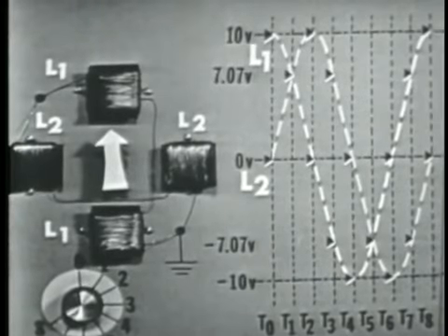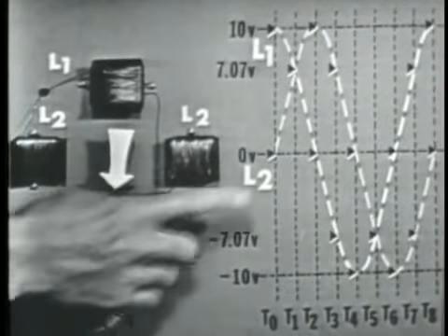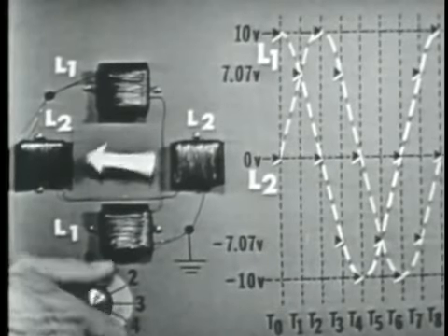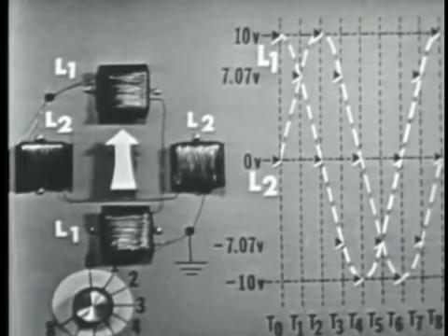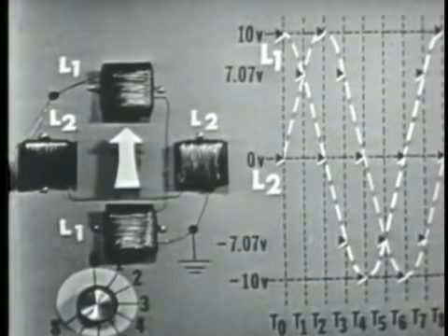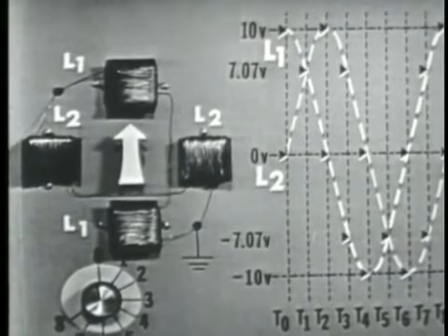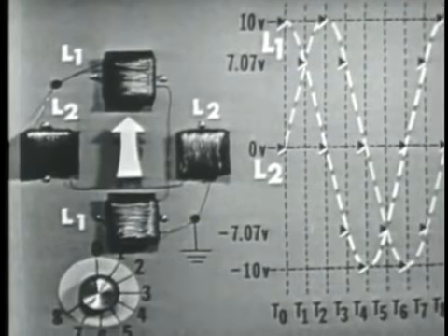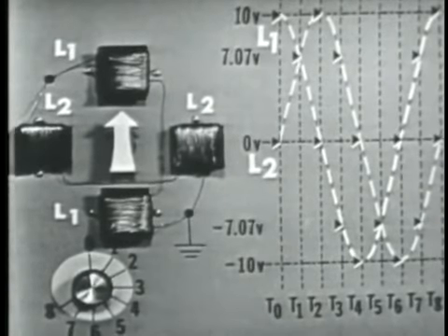Item 7 shows you how one complete revolution of the magnetic field is accomplished by applying these out-of-phase voltages to the stator windings. Now, you can study this very, very carefully so as to fix the principle in your mind. By the way, we might point out, Tom, once again, that you can apply the left-hand rule to all these coils and prove precisely what we've said, right? We can develop a rotating magnetic field. I'm certainly glad you said that. A rotating magnetic field that induces a voltage in the rotor, causing it to become an electromagnet, which will follow the rotating magnetic field. Simple and rugged and economical.